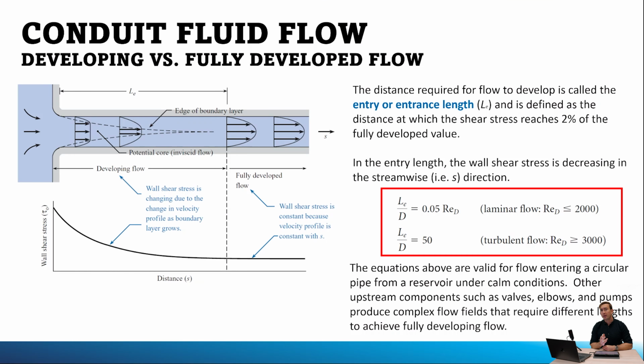So we're given some values down here for air and for water related to their values of kinematic viscosity, and we're going to use that information to actually calculate everything that we need to do. So let's take a look and figure out how we're going to do this. Step number 1 is going to be to solve for Reynolds number so we can determine whether the flow is laminar or turbulent. Once we have that, we can use our relationship for entrance length and solve for the rest. So let's first solve for Reynolds number for the air and then the water.